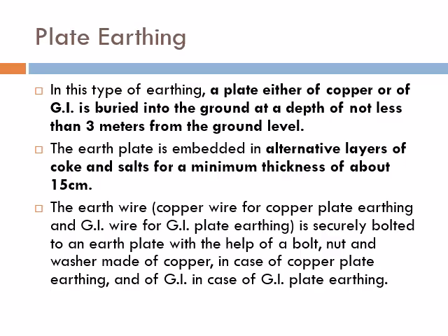It is securely bolted to the earth plate with the help of bolts, nuts and washers made of copper in case of copper plate earthing, and of galvanized iron in case of galvanized iron plate earthing.